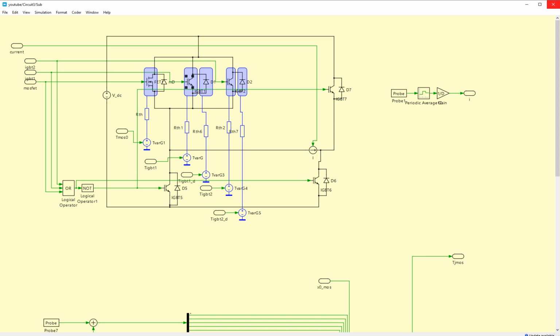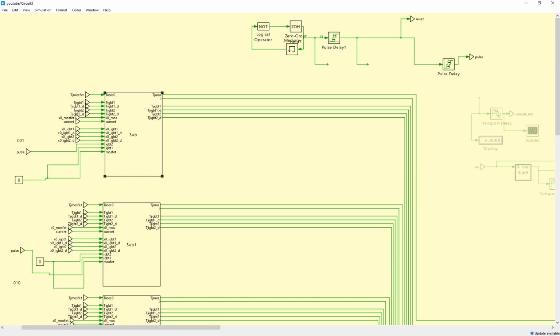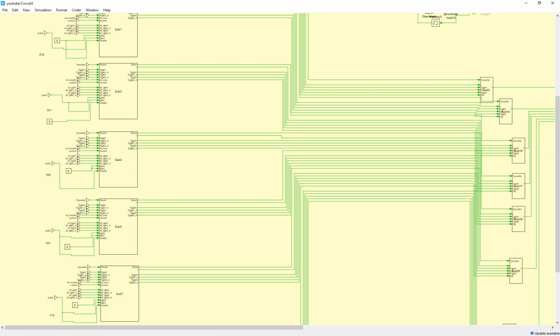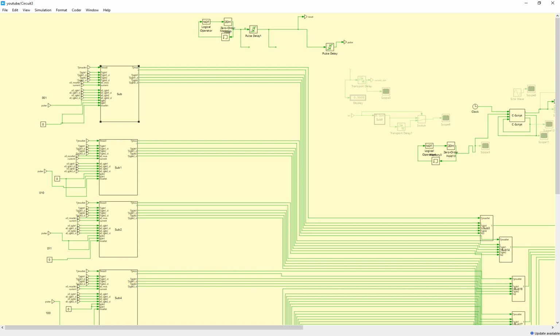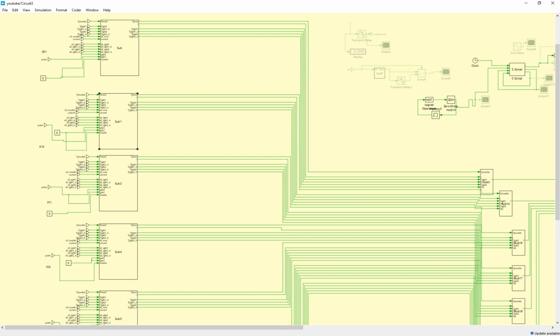But I'm running 7 simulations in parallel, and then I'm going to pick the best one in terms of efficiency or reliability or any other KPIs. They all provide different junction temperatures and different power losses because they have different activation, right? So the one that gives me the best for each switching period, I'm going to use for the next switching period.